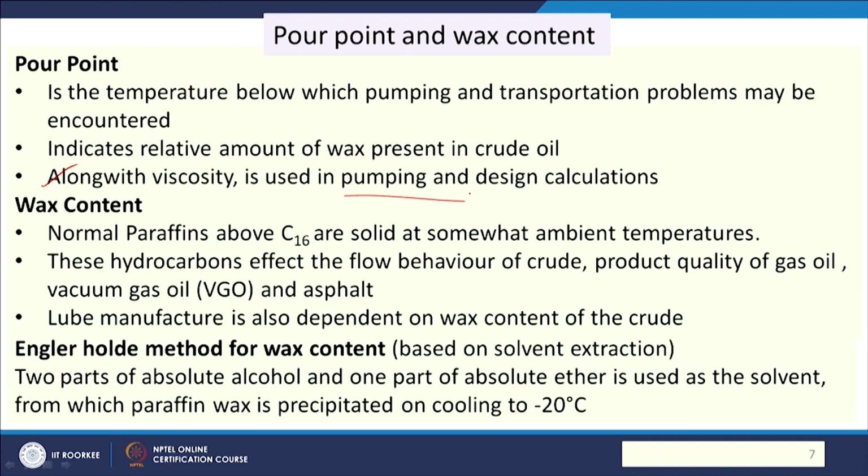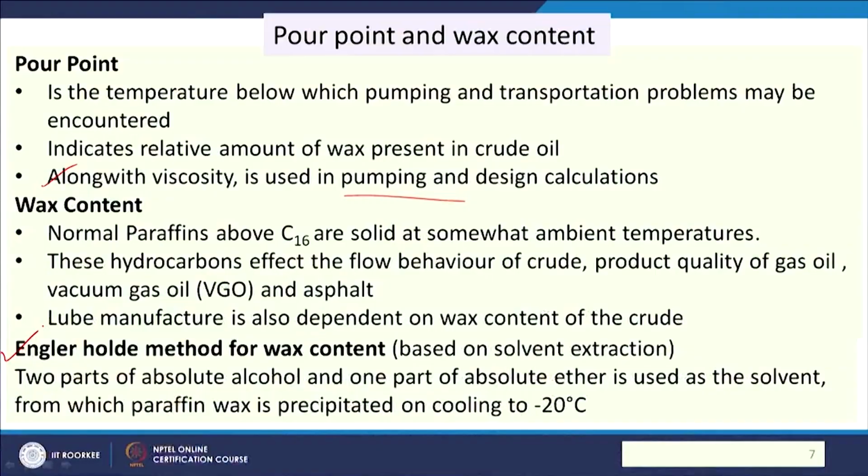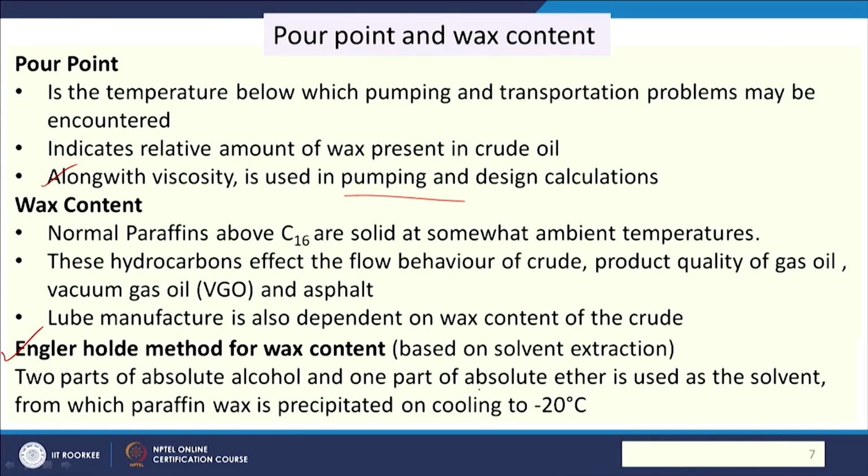And then wax content, as you know, paraffins having carbon more than 16 are solid. So, these solidified paraffins are considered as the wax in it, and this is determined by the Holde method, which is based on the solvent extraction method. As shown here, two solvents, absolute ether and absolute alcohol, are used as the solvent system, and then paraffin wax is precipitated at minus 20 degree centigrade. So, this is the method of determination of the wax.